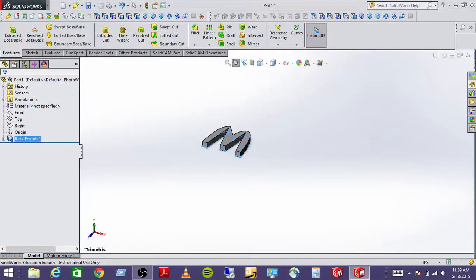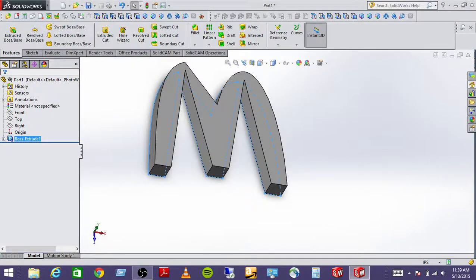One interesting engineering note, you guys might, just for fun, take your plastic and measure it with calipers before you go cut it, or maybe save some scrap and measure it with calipers. You're going to notice that 1/4 inch acrylic isn't really a 1/4 inch. Okay? It's significantly different. I think it's something like 12 or 15 or 16 thousandths different. That's a good lesson to learn. In fact, I'd like you guys to do that. I'm not going to assign it, but you should go do it. Next time you're in the shop, grab a pair of calipers and measure your plastic. Maybe peel back the little protective paper that's on the plastic and then measure it.